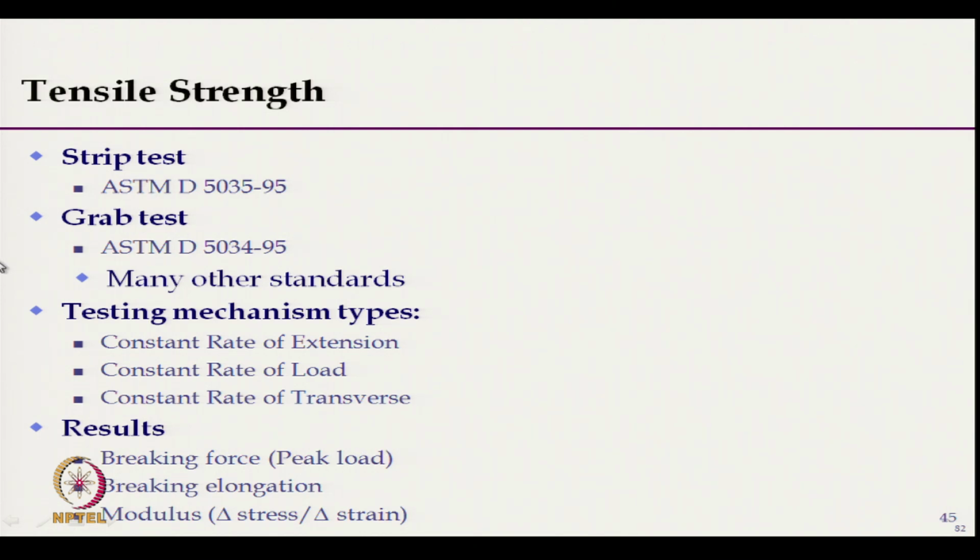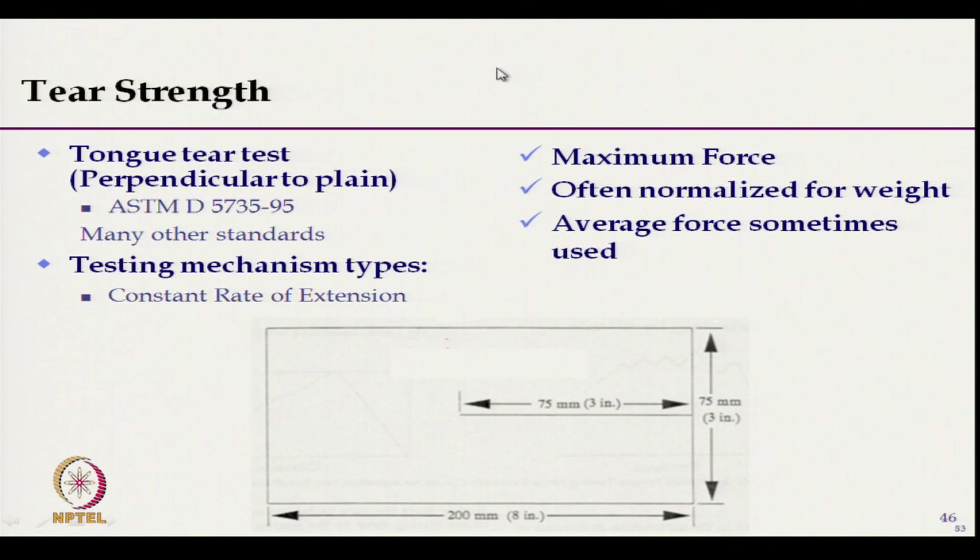So, strip test, grab test. These are the different tests available. Results are breaking force, breaking extension, modulus. These are important because during application or handling we must know the tensile characteristics of filter fabric.